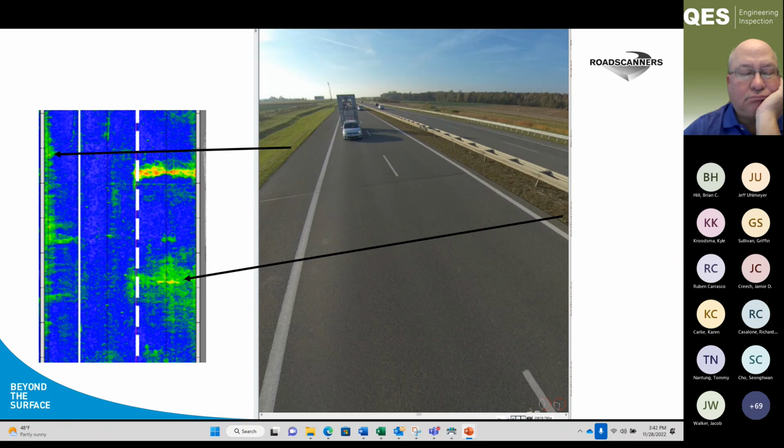Because stripping doesn't seem to take place if there is no moisture. For instance, in this case, on the top part, this arrow tells you that you have soil verges or crash verges, and because the water cannot go away from the pavement, it infiltrates into the pavement, and sooner or later you start to have stripping.